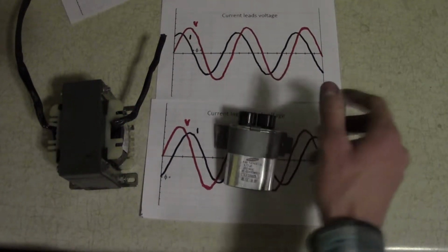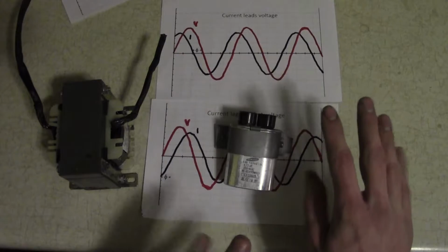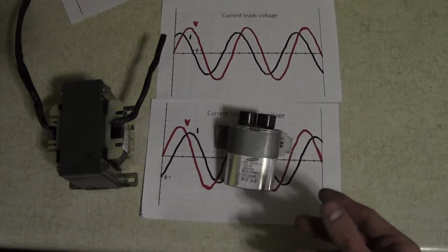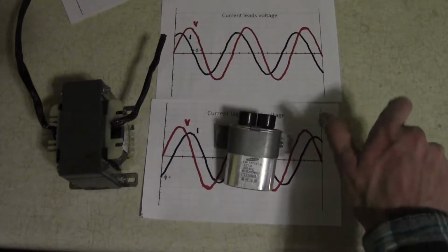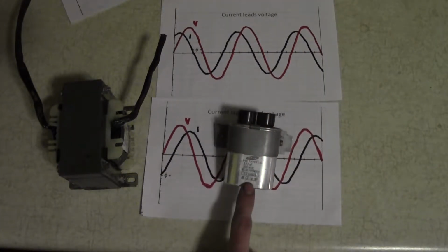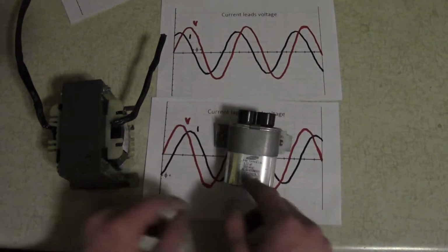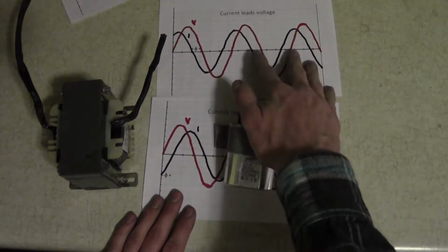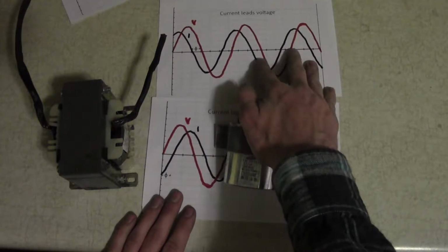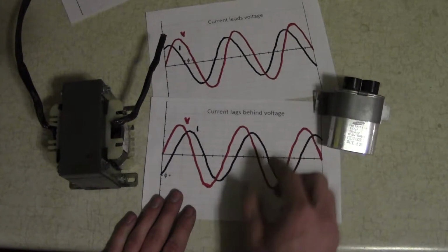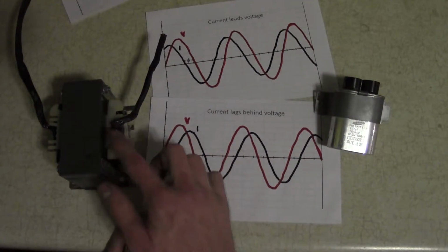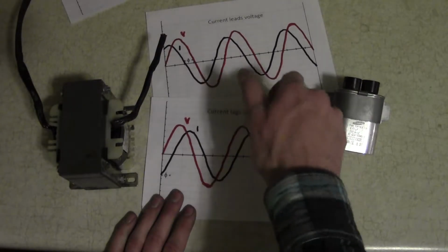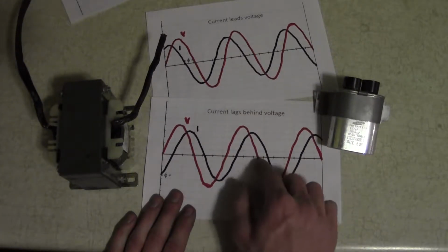I'm going to have some sort of switching mechanism, and we will come back to this when I have my final design, and I'll let you know what works and what doesn't. But I'd like to have some sort of knob, and the knob will increase the capacitance across my 120, and as the capacitance increases, it will move this current sine wave further and further to the left, and that will cancel out this inductive load, which has the current move to the right. So it'll move this here, and I'll just keep cranking up the knob until these two are about in line.